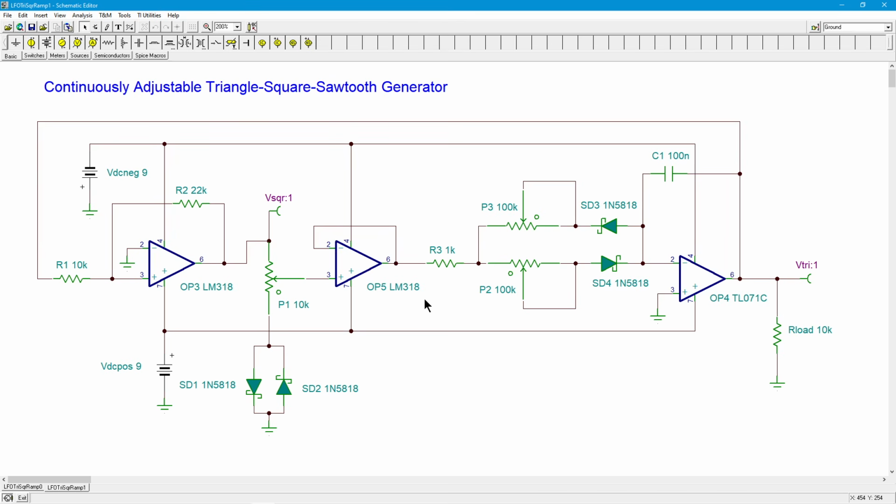No biggie. Your other option to prevent the loading would be to make this pot really tiny. Even at 1K, there's going to be a noticeable loading. I mean, if you brought this down to 100 ohms, the loading would be minimal, but now you got a 100 ohm load for this op amp over here. So this is going to run out of juice really quick.